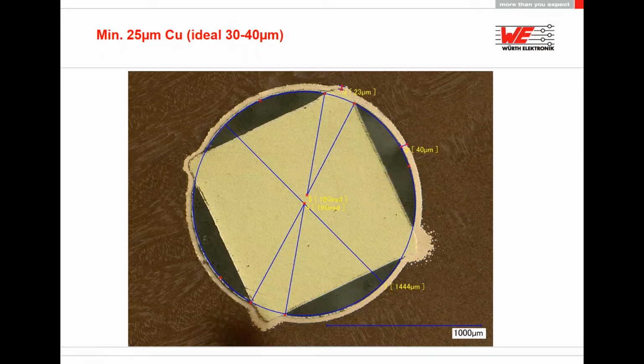The only thing we suggest is to use some plating on copper bars or brass bars, but it also depends on the application itself whether you need the plating or not. But with the plating, you can be really sure that there is no corrosion during the life of the connection.